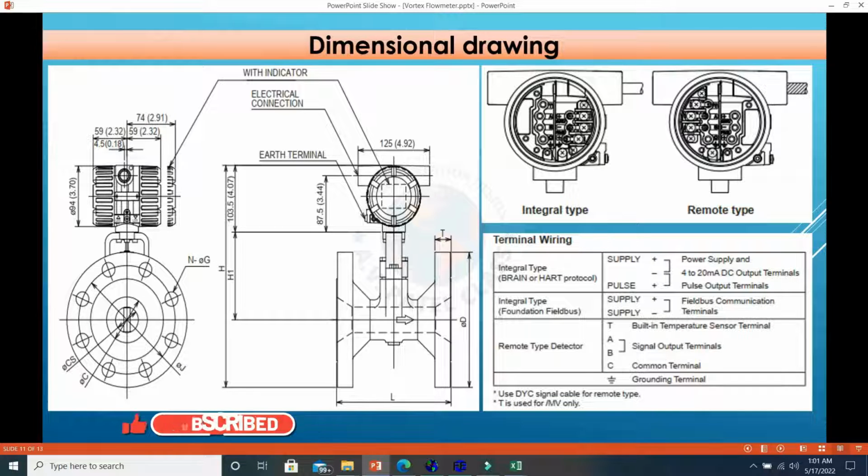Also, the mechanical department will use this drawing for making their isometrics. So we will share this drawing with the mechanical or piping department also. They will review and comment if any, and we can incorporate that comment as well, including our comments. In the same drawing, there will be some other drawings for terminal details. You can see there will be integral and remote types of terminal details according to the tag number, and we will use these termination details in our loop drawing and wiring module.